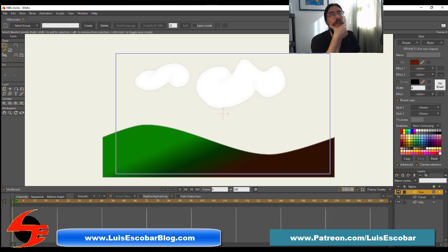Using the add point tool along with the welding feature, draw a shape that resembles the trunk of a tree. Here are a few things to remember as you go. First, you can always use the edit undo command, blah, blah. Second, you can switch to using the transform point tool to reshape parts of the object even if you haven't finished drawing the whole thing yet.